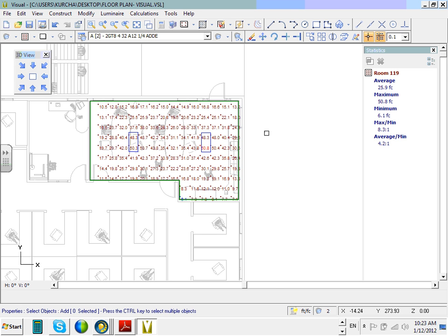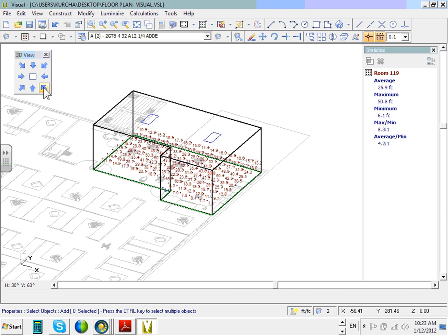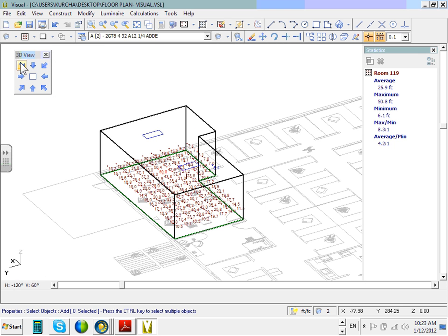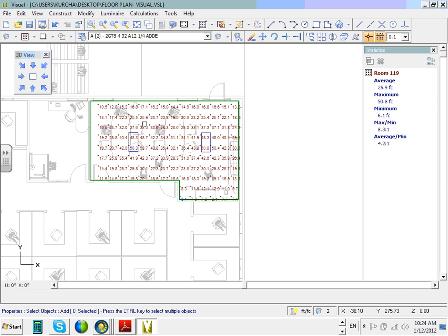So this is, by the way, give me one second here. You can look at the 3D view of your model that you've done so far. Say you made a mistake and you deleted something. So my friend made a mistake and deleted something. So let me just make a mistake and delete something, right? Look at this. I accidentally wanted to delete a fixture, but by the way, if you go right to left, you pick everything that you touch, like CAD. You go right to left, you pick everything that you touch. You go left to right, you pick everything that you enclose, like CAD.